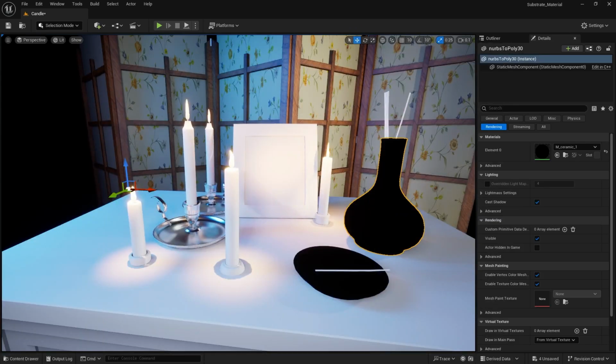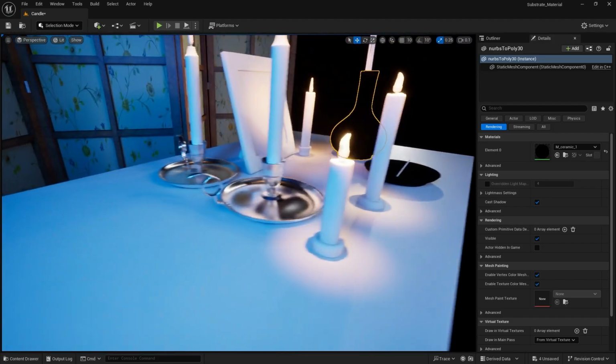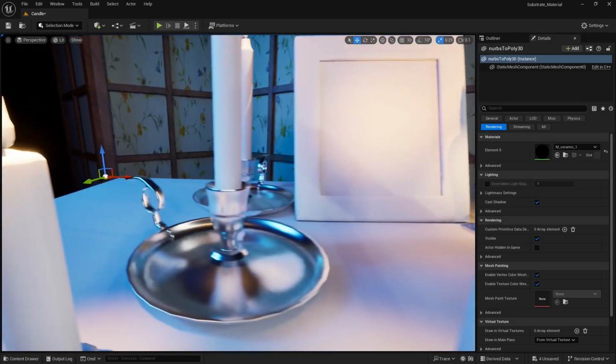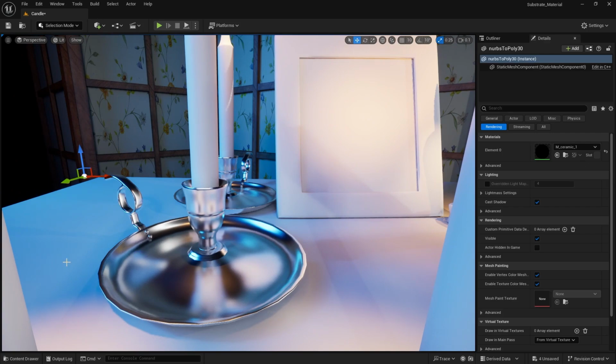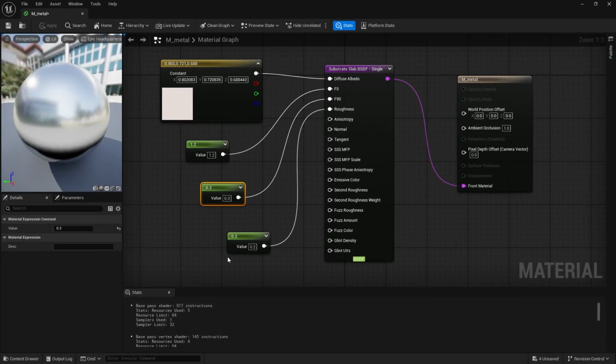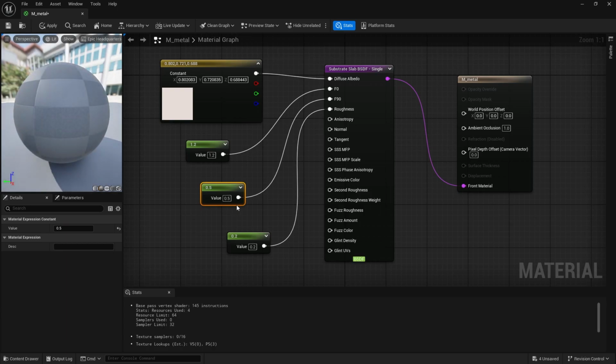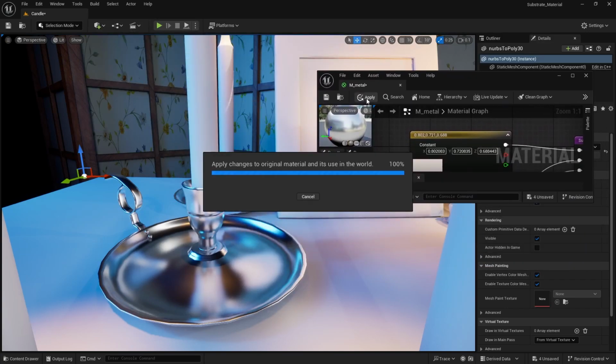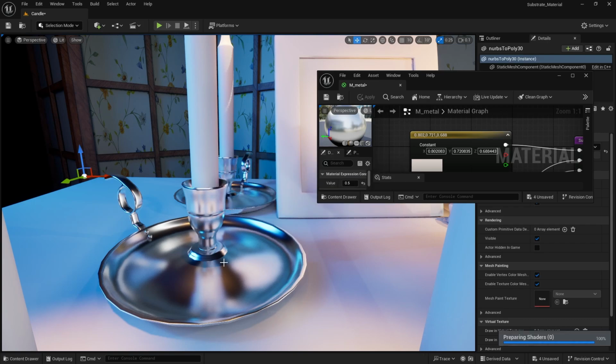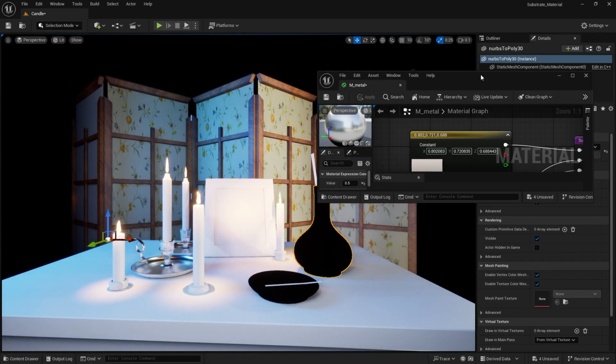Once applied, we can check that material out in our viewport. It looks good to me. F90 is this specularity amount. Let me go back to the metal material. See, F90 is basically giving us the color values coming from the 0 to 1 scale, like black to white. So I'm going to set it to 0.5, because I would like to go with the default white or maybe gray-white tone of the color. Then I check it out by applying. If it is partially or somewhere visible, okay, it was visible. See, if you noticed, it showed a little bit of change here. But yeah, the material looks good to me.